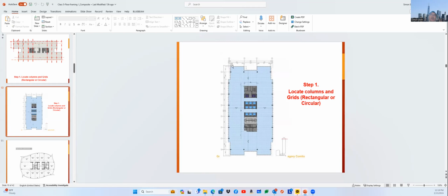This is an engineering judgment, and collectively you need to discuss it with your owners and architect, so that we can determine the column location that works best both structurally and architecturally. Looking at the span length from here to here, maybe 30 to 40 feet. If we push this one another 10 feet outside, the span becomes much longer, 40 feet, which is relatively long and might end up with a big beam depth. Also, architecturally they may prefer the column inbound and a cantilever space. I think this example is a collective idea that ended up with this column layout.